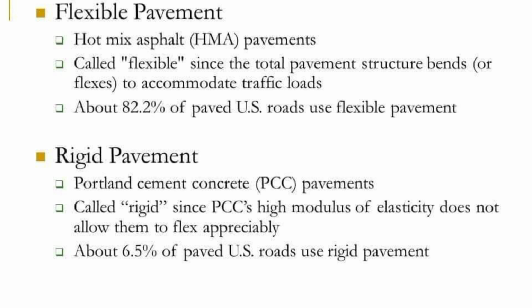And when the Portland cement is used as a binder, then the type of road is known as rigid pavement. When the rigid pavement and flexible pavements are used both at a time, especially in the case of airports, rigid pavement is provided, and then for flexibility an overlay of flexible pavement is also provided.